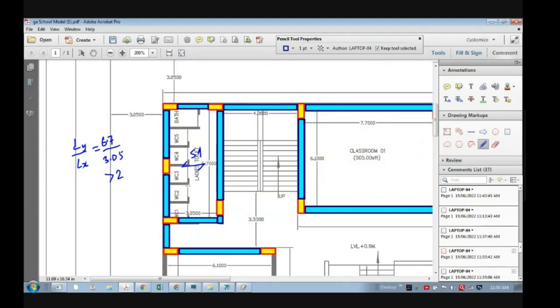Now tell me, so we have decided this slab spanning. How will the staircase span be? By default it will be one way, sir. Yes, staircase, all of you know that in a staircase the flights are inclined flights. That means there cannot be any two-way condition. It will be one way only. Will the staircase be one way or two way?